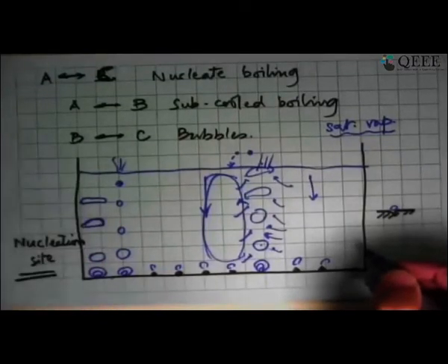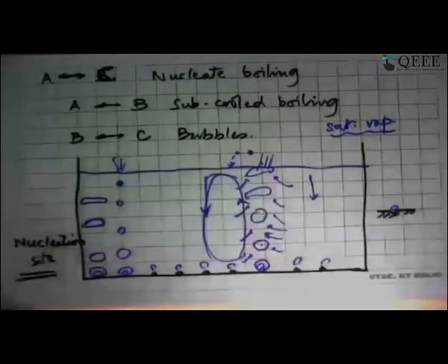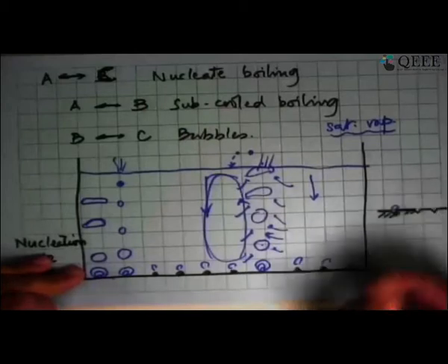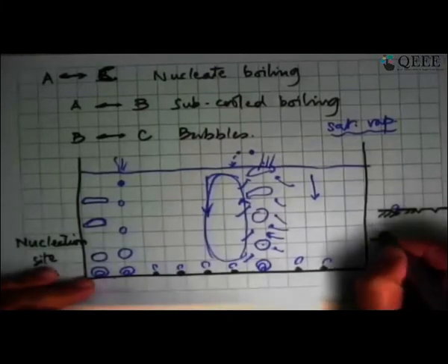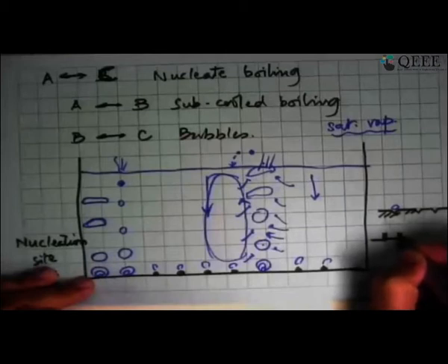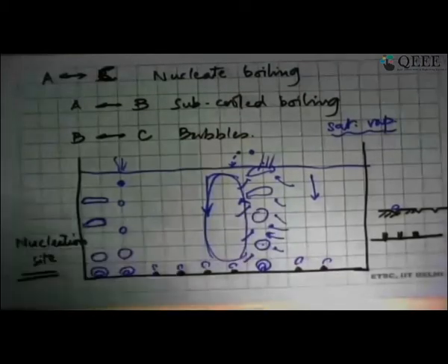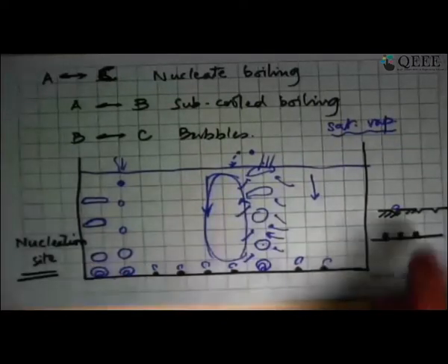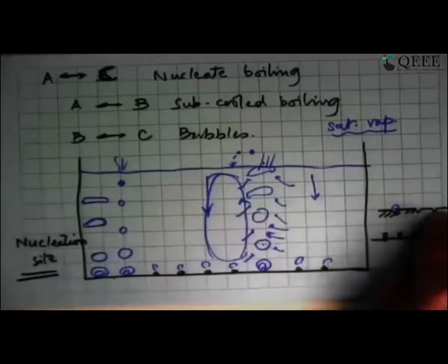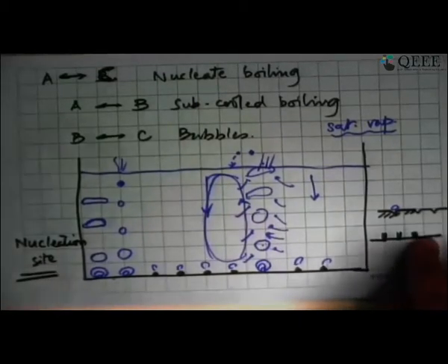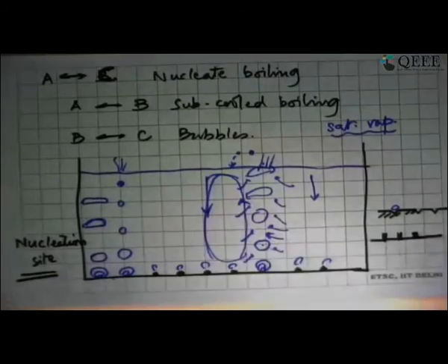If you would like a very large heat transfer rate, then the objective of the designer would be to make lots of nucleation sites on the surface, by putting a roughness here and a roughness there and things like that. You basically have to roughen the surface, either by making lots of small micro ditches or grooves, or by attaching little roughnesses to the surface. That's a challenge on the manufacturing side, and if you can do that, you get much higher heat transfer rates.